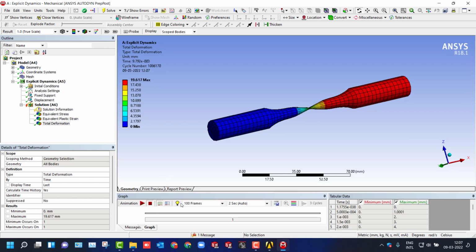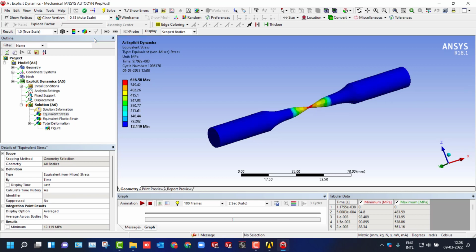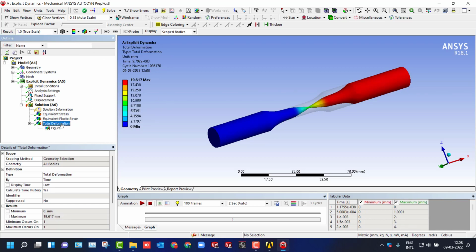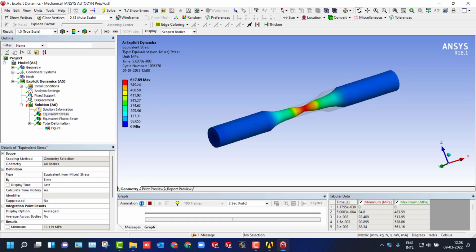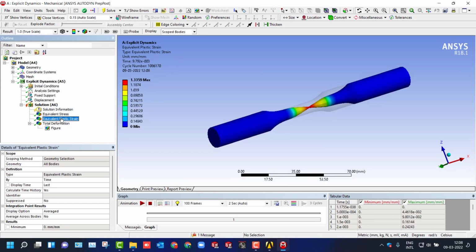So this is the displacement plot, and you can use the different types of plots by using these plot options, and then you can choose the contours like smooth contour, and we have better visualization with this, embedded with the practical model with deformation.